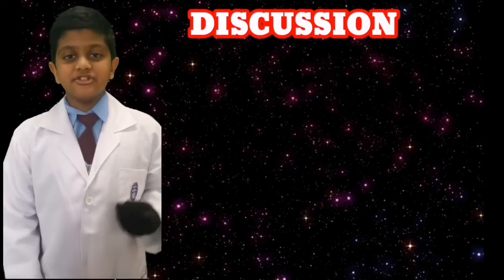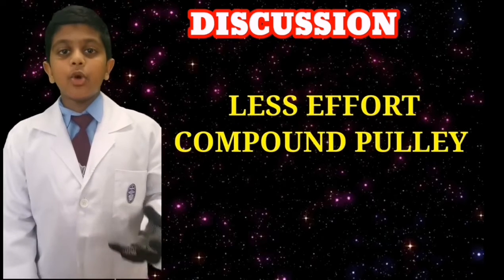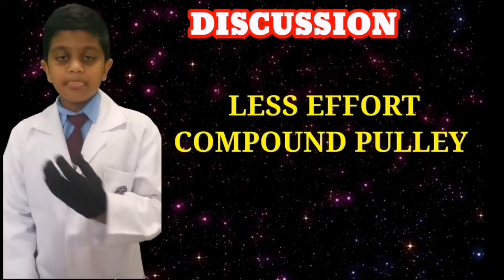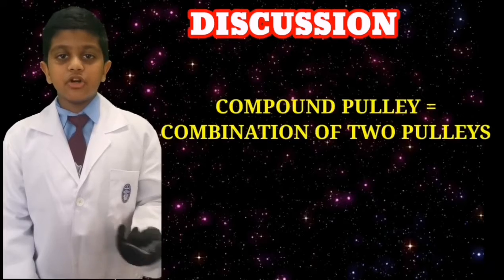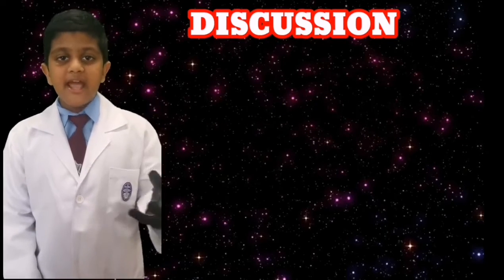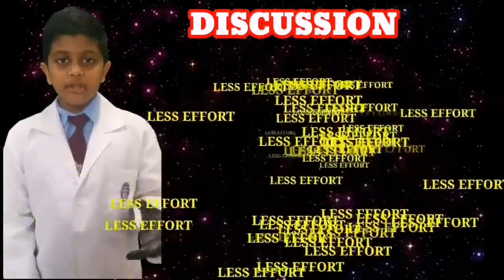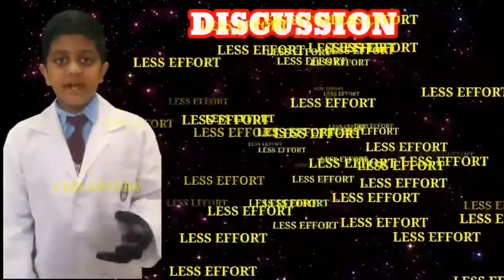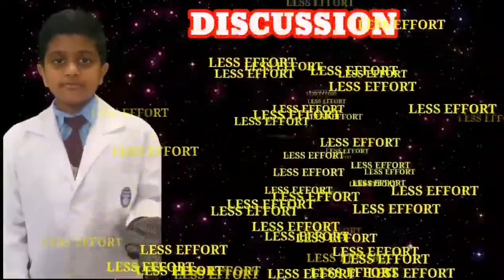Discussion. Based on the results, we found that we use less effort in the compound pulley compared to the movable pulley and fixed pulley. This is because in the compound pulley, we use a combination of 2 pulleys. It is designed to make the effort less than half the weight of the load. Using a compound pulley, the load will be much easier to lift up. The more pulleys that are attached, the easier it will be to lift up the load.